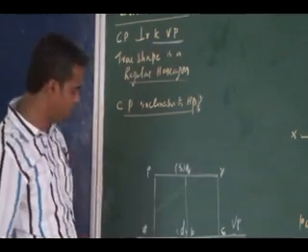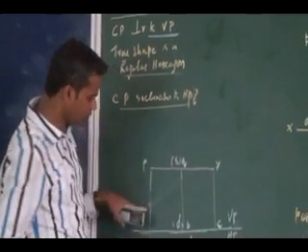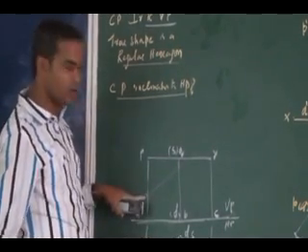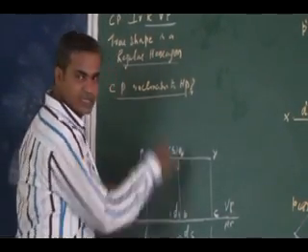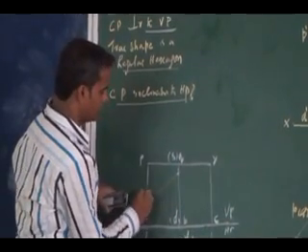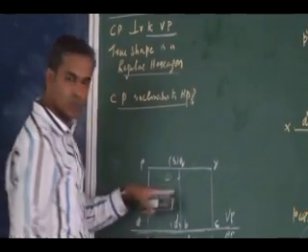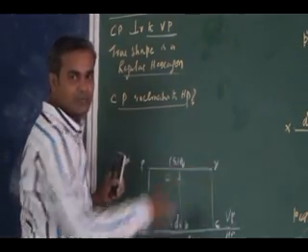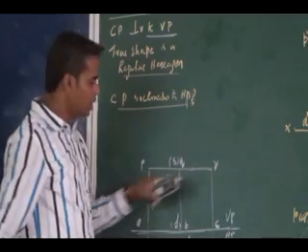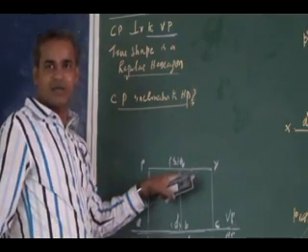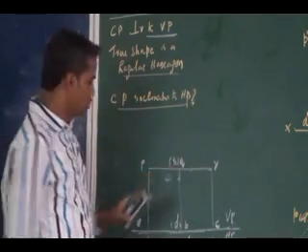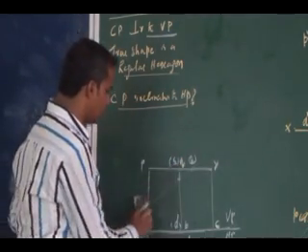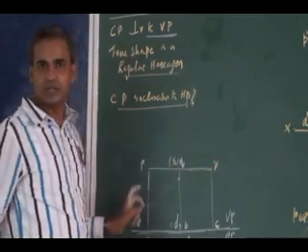So how many cutting points will I get? You can see here, I have only one vertical edge, that is AP, so I will have one cutting point. Here I have two vertical edges, so I will have two cutting points. So totally three. Here it is a base, it passes through the base. Totally on a base, if a plane cuts, I will get two more cutting points. So totally I will have only 5 cutting points.